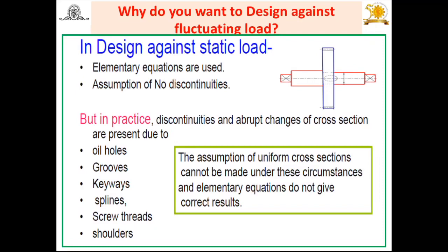Because in actual practice, discontinuities or abrupt changes of cross section are present on machine elements or components. This is due to oil holes, grooves, keyways, splines, screw threads, shoulders or fillets, and steps that are provided. All these are discontinuities, and because of them the stresses induced in the component are far higher than the stresses calculated by using the elementary equation that we used in design against static load.